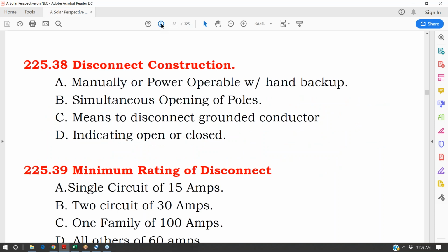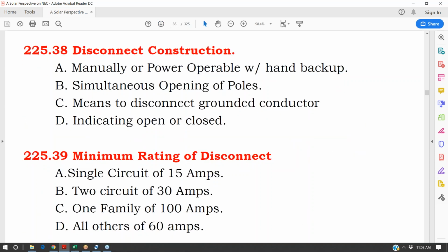With our disconnect switches, there's a few different kinds. I've started to find some disconnects that are for smart homes that can disconnect remotely. The main thing when you're looking at machine operable, remote operable disconnect switches is to qualify as the actual disconnect and not an auxiliary or secondary disconnect. They still have to be manually operable.